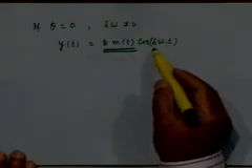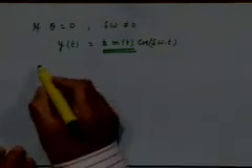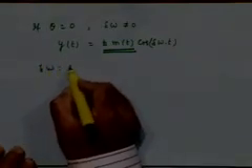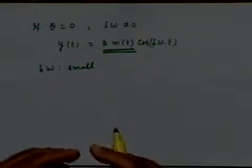And in that case, cosine delta omega t will be a slowly varying cosine wave multiplying your m(t), right? Delta omega is typically small. So what will you see? You will see that your incoming signal is multiplied by a scaling factor, which is sometimes going up and sometimes reducing significantly.